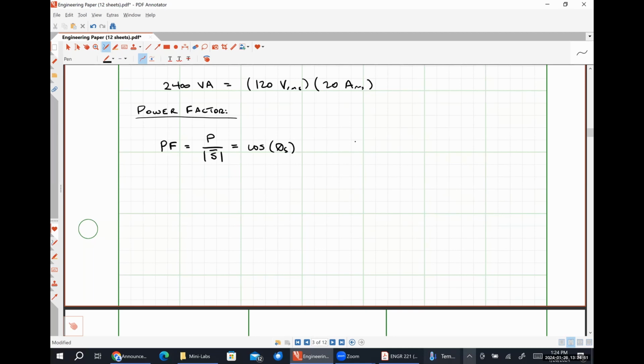And that's why we tend to view it as a measure of efficiency, because it can mean we're either 100% efficient in consuming power on one side of the spectrum and 100% efficient in supplying power on the other side of the spectrum. And there in the middle, when our power factor is 0, means we're doing a garbage job of supplying or absorbing the power in our system.